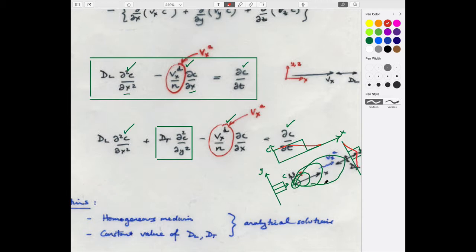And so, two questions. One is, is this going to be a good estimate of where the 50% mark should be? Or would it be something that might look like this, or might look like this, completely away from this? And secondly, when we look at two-dimensional or three-dimensional behaviors, how do we accommodate this lateral spreading? The answer is in the equation: we look at the concentration gradient across the width in the y direction, and the amount of spreading that occurs results from that.